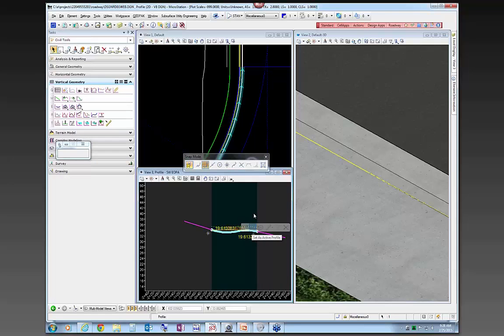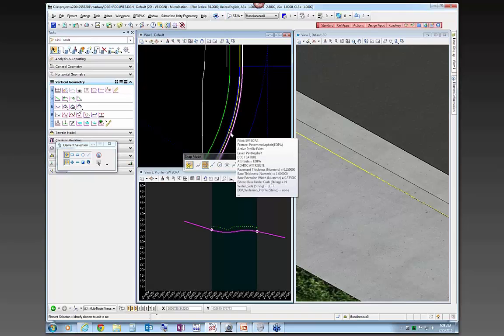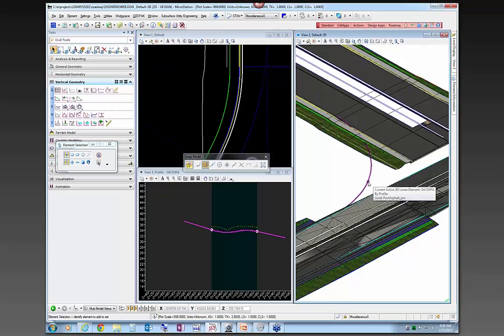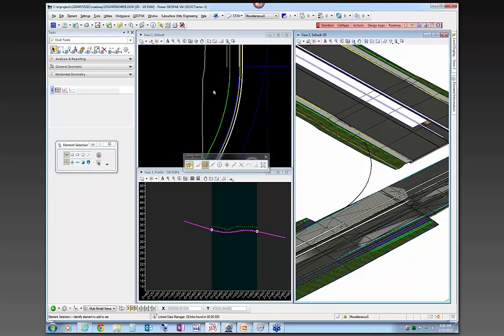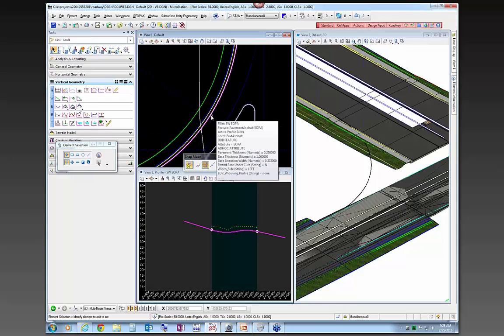Now, another thing that you could do is if you wanted to save this out to your GPK and then either construct a profile using the legacy tools, or you already have that profile in that element, you can import it to it, and then once you have it, you're just going to set it active. And then by setting it active, you're basically creating the 3D element that is that line. Okay, so if you think back to the slides, I said we're going to use the profile tools to create 3D elements from our 2D elements. So that's essentially what I did right there.